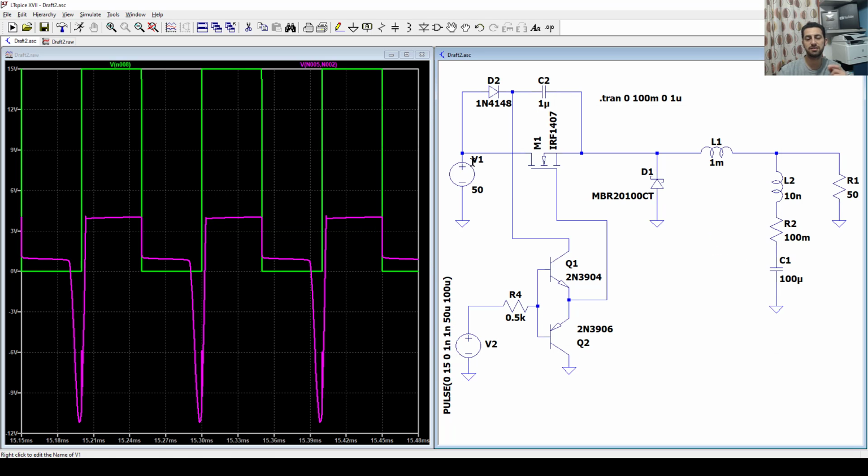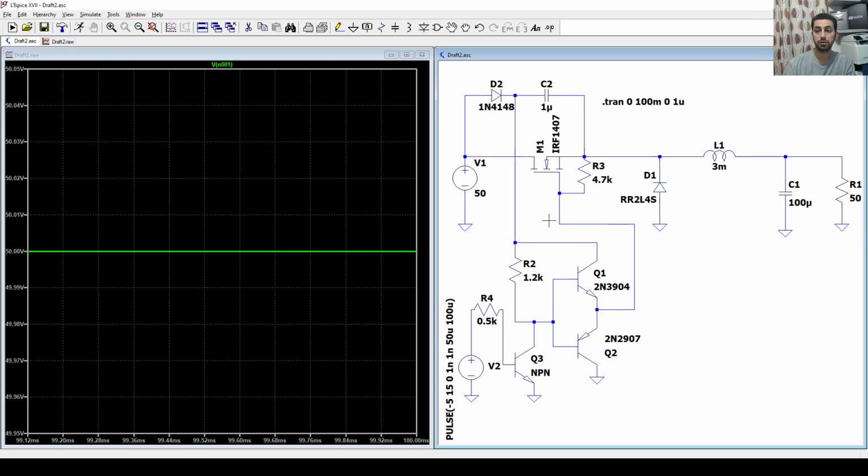It's enough because it has just to deliver for a short time and also a small current. So this is how we use our Bootstrap Capacitor to drive our high side MOSFET using the push-pull configuration. That push-pull configuration now will take the charge from that capacitor during the on time. So when this turns on, or the on time comes here, that will turn on and bring the charge of that capacitor to the gate.